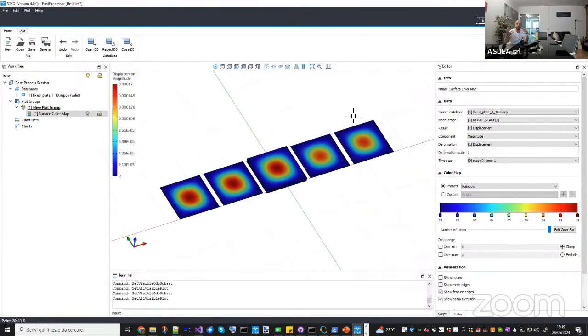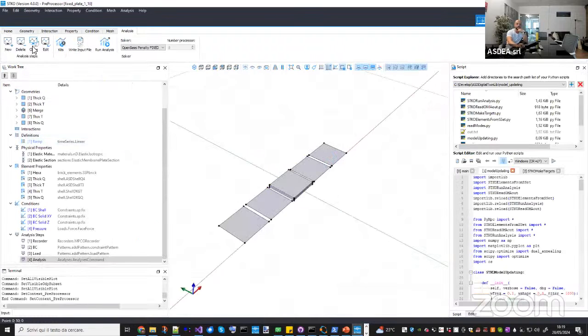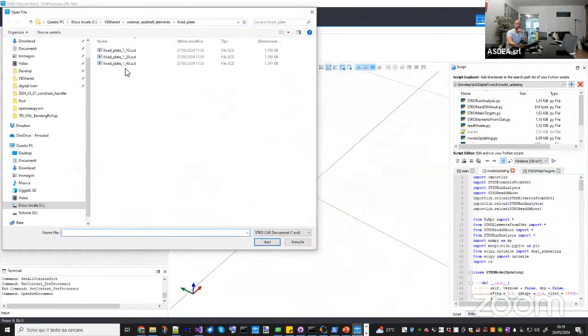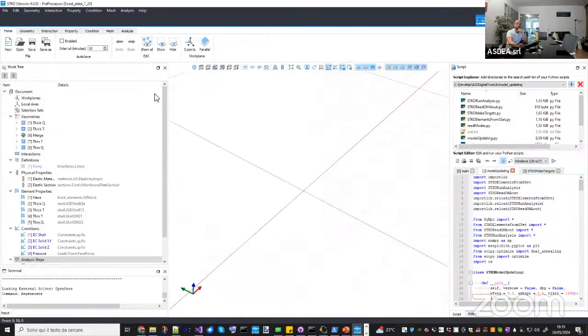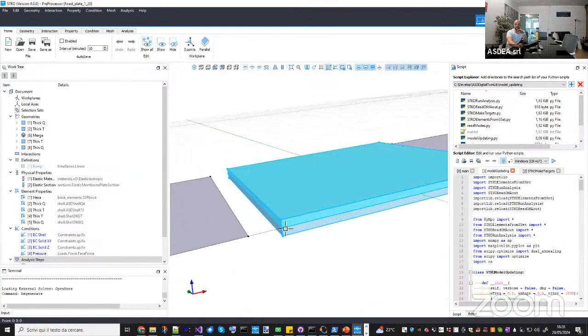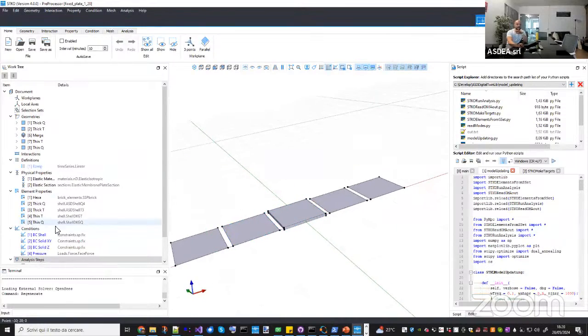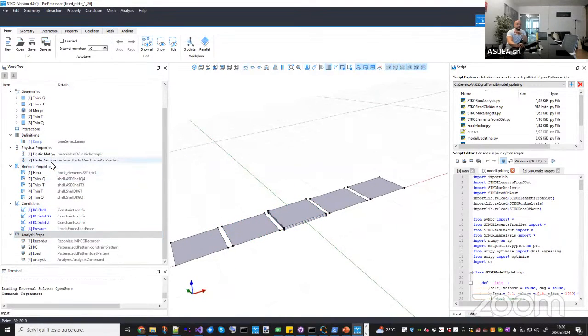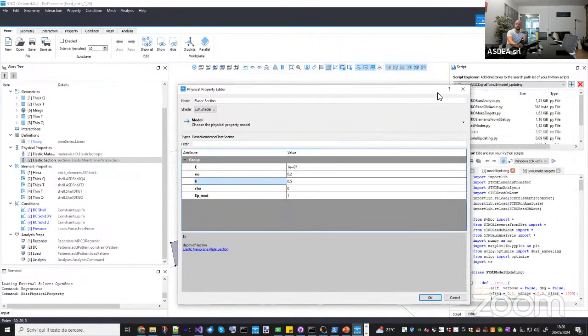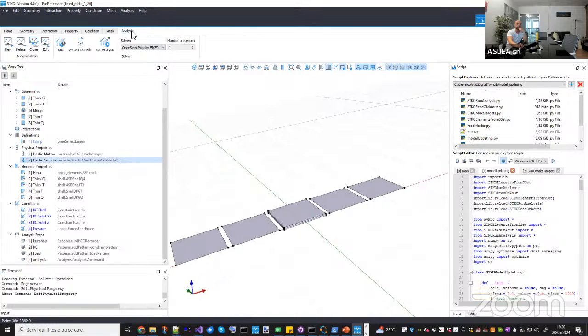Now, to see if the thin shell element converges, you can try smaller thicknesses, like we can go to the 1 to 12, 1 to 20. Okay, this is the same file. I just scaled the solid thickness, and I changed, of course, the thickness of the shell element. Okay, so now it's not 1 unit, it's 0.5. Okay, so you can run this other one.